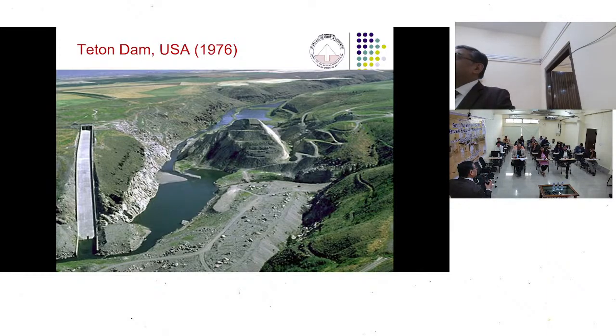And aggregates are used in concrete dams, and dams are going to have a water face. So the aggregates in the dam body react, they form cracks, and once a crack is formed at the dam face, more water is going to percolate inside, and so the aggregate which is further inside is going to crack, and more water is going to percolate, and finally you have heavy seepages.